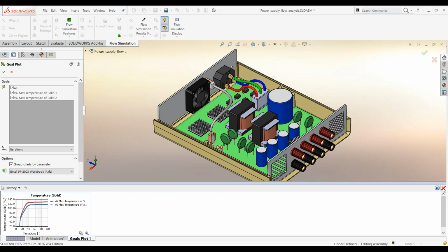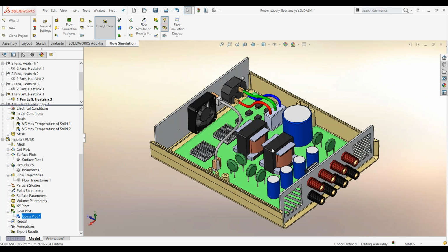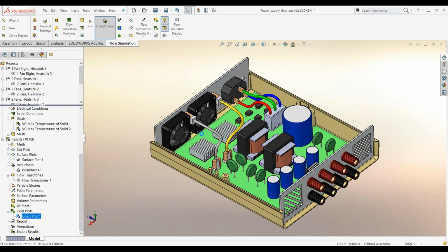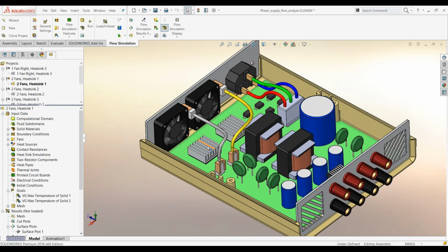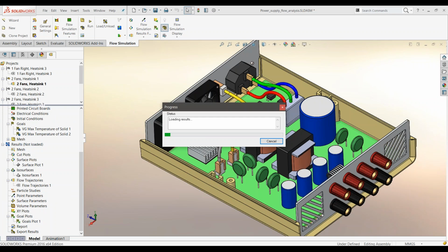we require. So the workflow here is that you get the results and then you go through different studies, adding in different scenarios. Now we use the different types of fan studies and so forth, and then look at how it goes again and again, with different iterations. So let's look at different types of heat sinks, and with the two fan scenarios, what will happen.